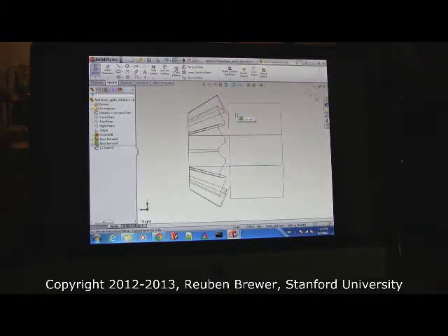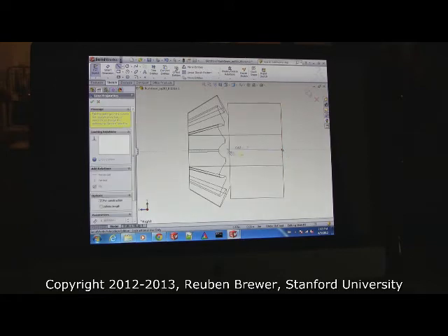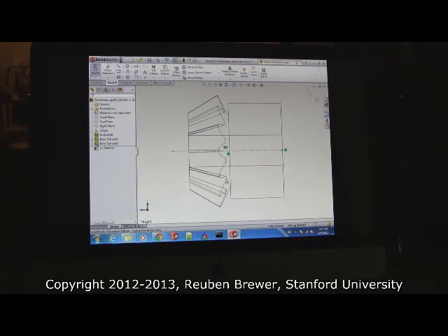Okay? Now I want you to take a construction line. See this? When you put the start of the line along the midpoint here, we get a midpoint constraint. This is one of the most useful things in all of SolidWorks. Click there and drag left and see how it wants to snap horizontal. Let it do that. Hit escape.